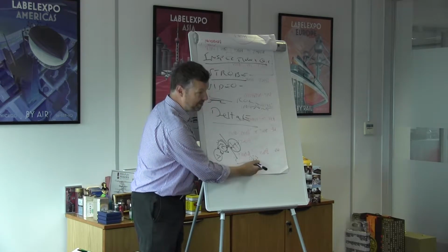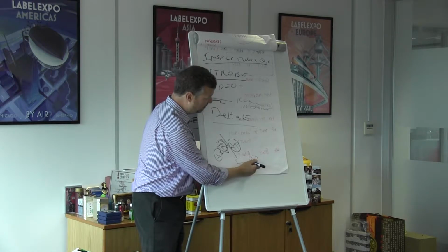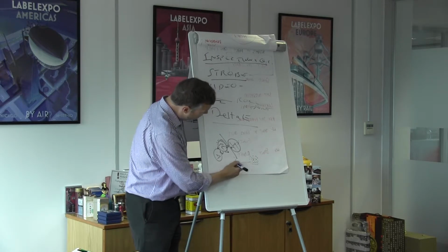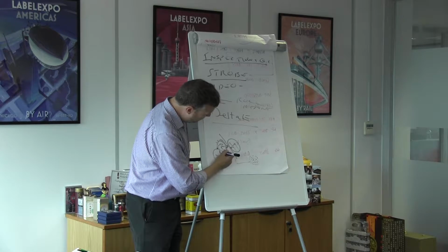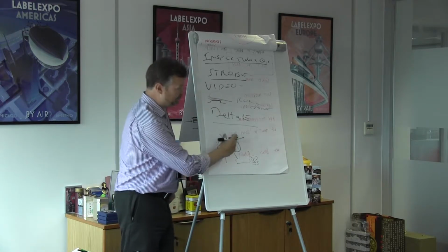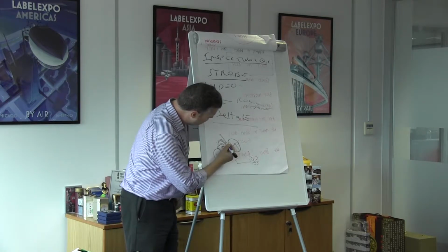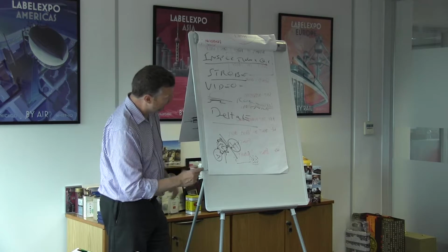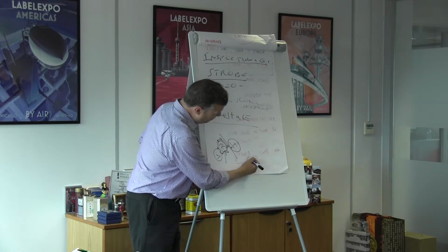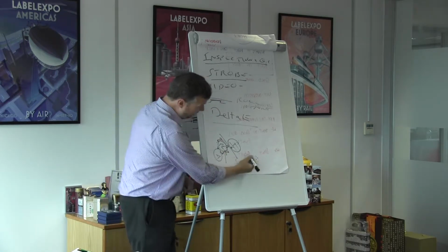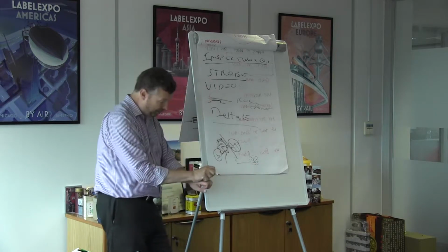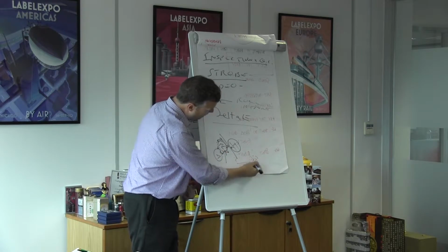So as soon as the camera sees that happening, it says, right, it's too much pressure. So it sends a message to the servo motor controlling that and just tells it to back off. It just backs it off. So you have a little motor here on this cylinder which moves it this way and that way. Okay, so if there's too much pressure squashing, that image is going to get bigger. So you just back off the pressure until it comes back to the right size again.